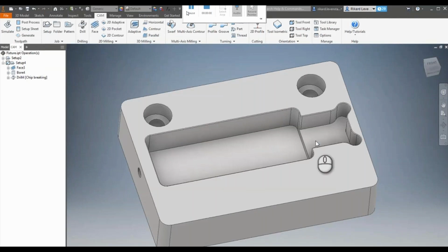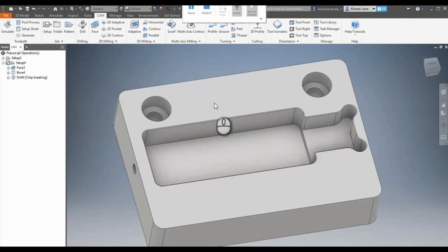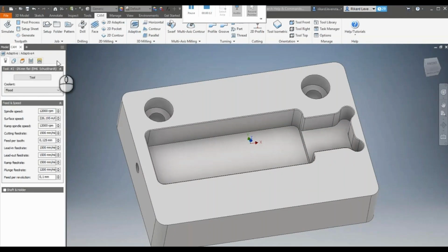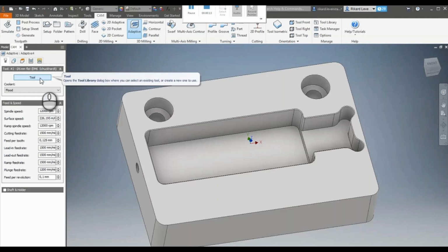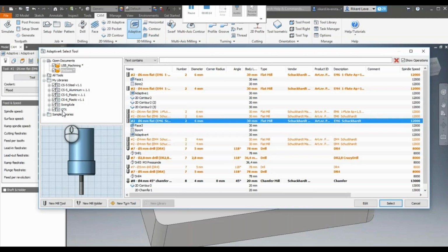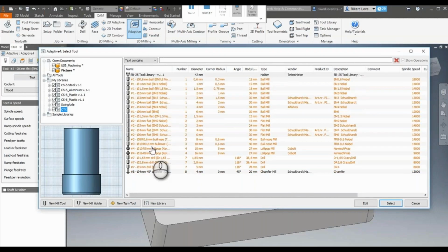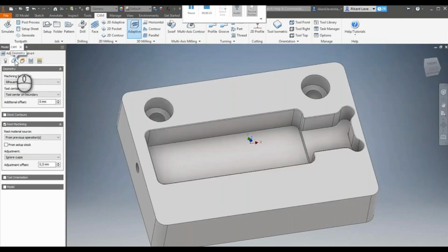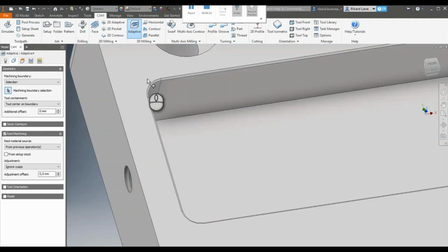So we're still using the 2D milling strategies in here. Previously, you could use adaptive clearing on the 3D milling strategies. And in here, firstly, select the tool that you're going to work off. Go into the flat end mill, select that. And again, the geometry. Geometry is important in here. We've got to choose either a selection or silhouette. If you go into selection, it's important to have a good view of your selection.